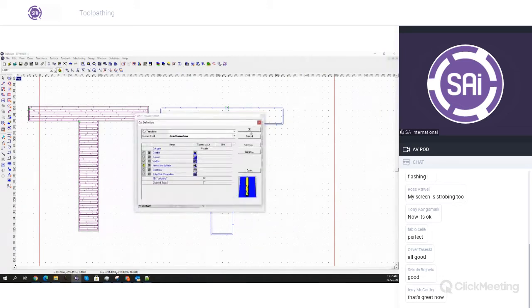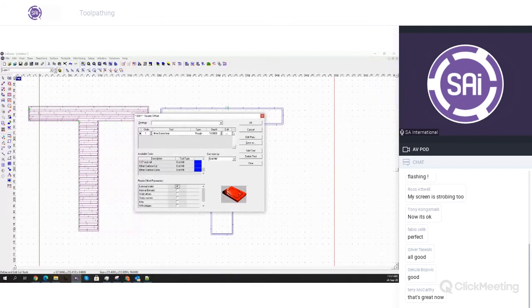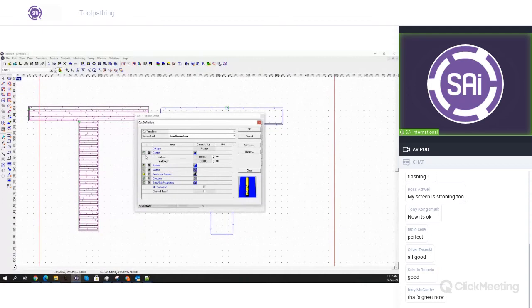So going further, hitting the three dots here, you can hit the properties of your toolpath of the specific tool. So here you'll be able to define the depth. The final depth will be 10. You also have the possibility to offset the surface. Let's say you've already made a toolpath that is being routed before this one, and it has already cut away like 4mm. Then to reach the depth of the plate, you would have to only route 6mm deep. So the final depth is always in relation to the surface.